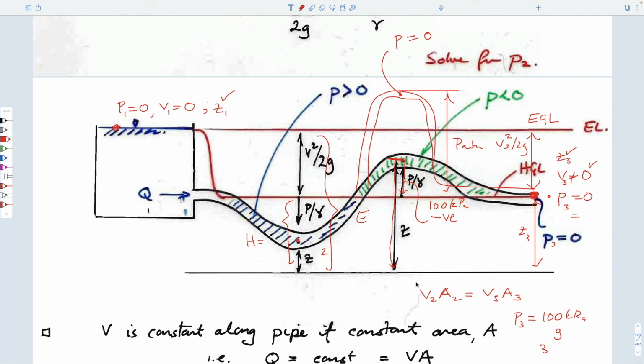When it starts off at atmospheric pressure on the left-hand side, it goes up through, becomes 0 absolute at the top. The water comes out of solution. You put a little bottle up here that allows it to go into there, and this bottle fills up with air as it cavitates, and then water comes down the other side into your beaker. So that's it. That's what we've talked about.